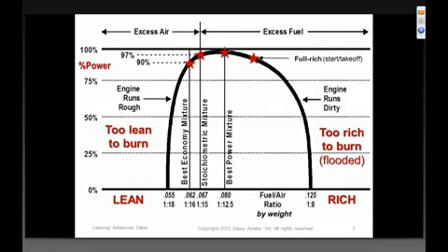at which we lose some power and a little bit of airspeed, but we make up for it by getting the best brake-specific fuel consumption, the minimum brake-specific fuel consumption, which you can think of as the inverse of miles per gallon. So it's the best miles per gallon, if you will. That's best economy mixture. And if we lean beyond best economy, the engine loses power very rapidly, starts running rough, and eventually will flame out.